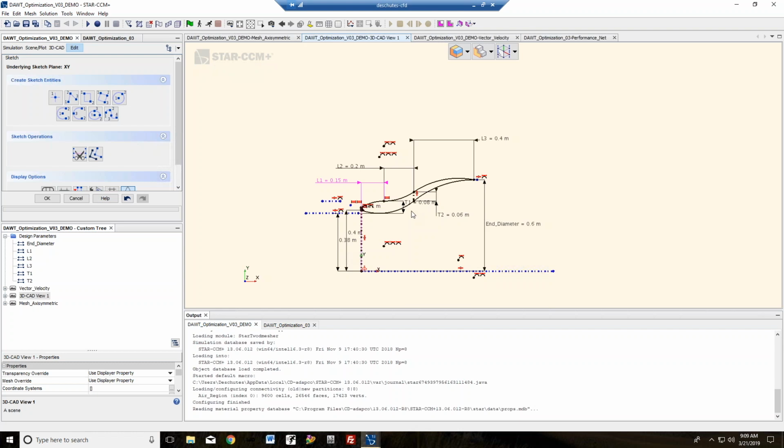A lot of people talk about wrappers, but in CFD you really have to have it, because very tiny features don't really affect anything on your mesh usually, and if you can just blend those together and cover it with a skin, it's going to be a lot better numerically, and you're going to get a better solution. It also enables you to take very large assemblies and do these parametric and optimization studies, because the wrapper is integrated into the tree. When you change the parameter in NX, it brings the geometry back in and automatically reapplies the wrapper, sends it through the tree, and boom, into the optimization.